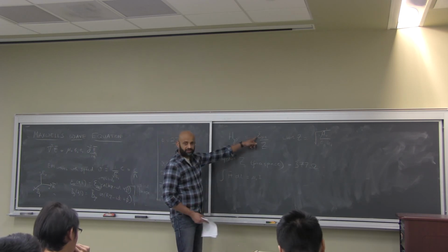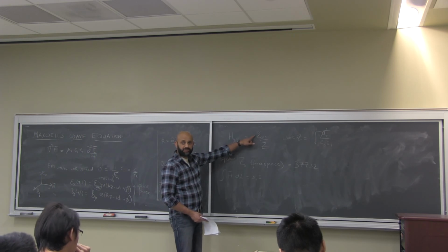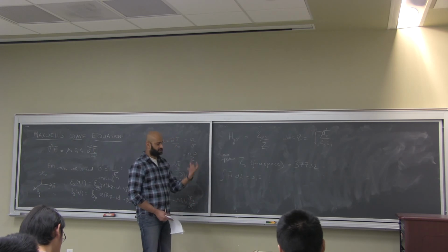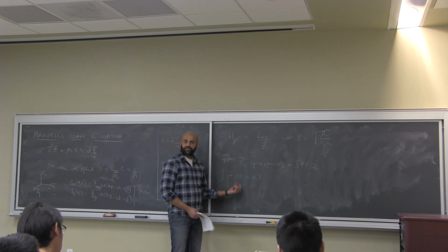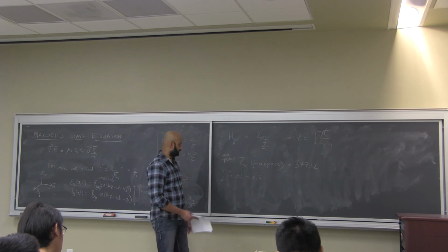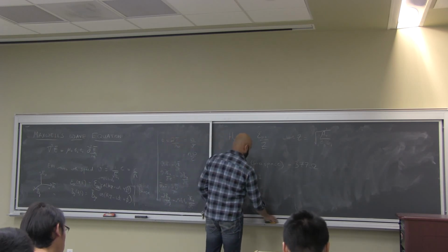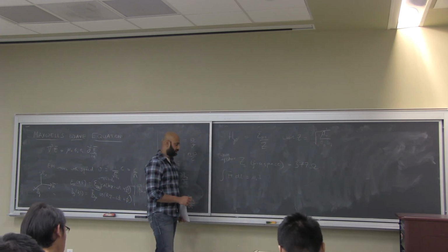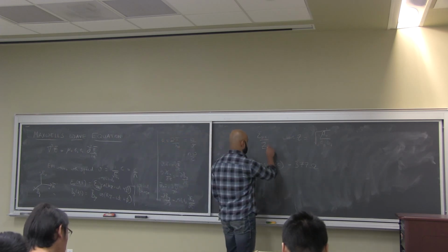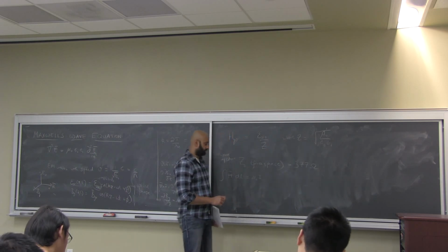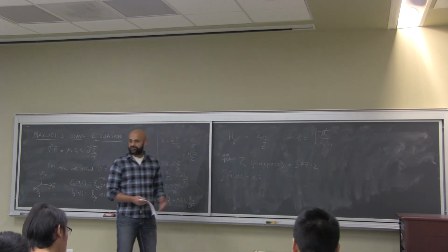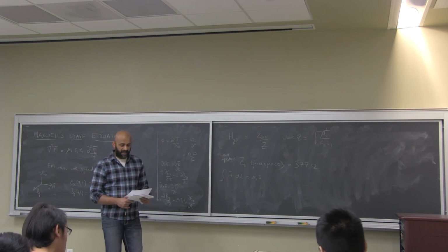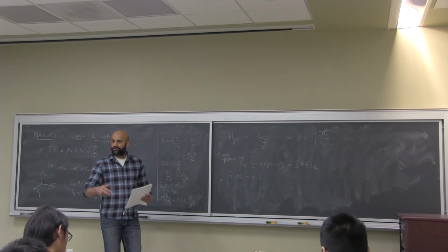Similarly, you can do the same thing for Ex naught. That will give you the potential. And so we see that the potential across the surface is related to the current in this formula by the impedance. So the current equals the voltage divided by the resistance, which is Z. This will be useful, especially when you consider things like matching of impedance between two different media.